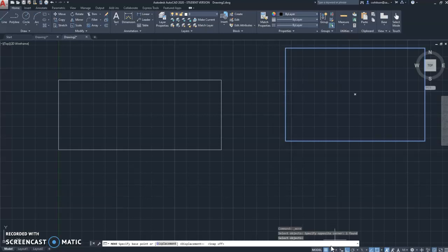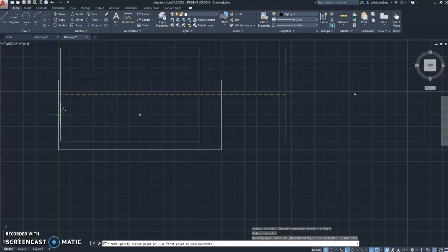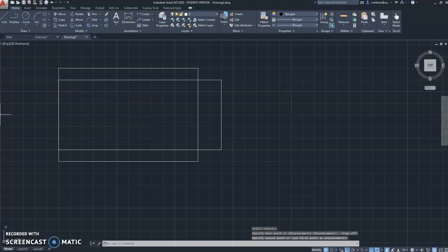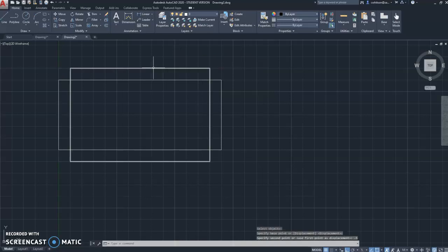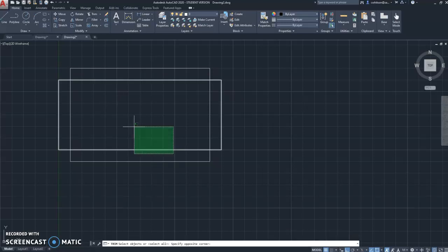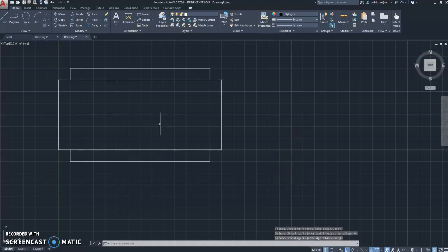I'm going to move it. Let's check my object snap. No, I do have midpoint turned on. There it is. Midpoint of that line to the midpoint of that one. And then with the horizontal difference of 1 inch, that means I want to move this one over ½ inch. Okay, and then I'll trim that dimension like this, those lines like that.